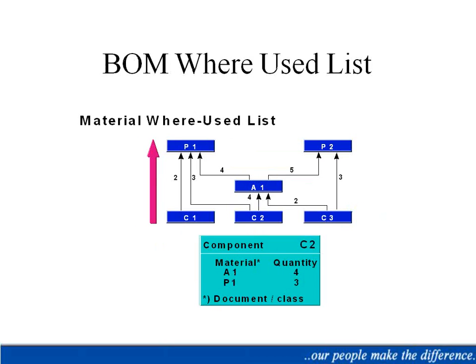So this where-used list is very easy. Whenever you want to make changes, replace any material, or see the effect of a change, for example if I change this particular material, what are all the BOMs, components and assemblies that are going to be affected, you can see it very easily. It is not possible for us to remember where each material is used, so in SAP there is a functionality called the where-used list. With this, you can find it out. The moment I specify a particular component, the system will tell you that you have used this component in these assemblies. Can I proceed, Chandra?